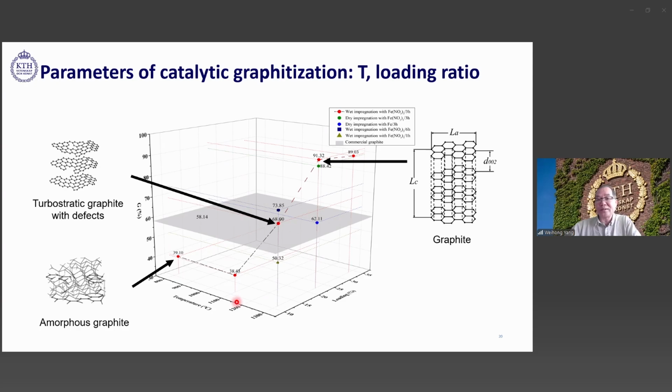then you have different applications. If you target battery applications and steel and iron making, then you have to come to here. If you come to other applications, lubricants, reflective materials, then maybe you can stop in here, or even come to the other, depends very much on applications. Which means in principle, when we have the catalyst and the temperature over 800 degrees, most of the carbon starts to convert to crystallization and graphite. And for complete graphitization, you will need more time, more temperature and more catalyst.